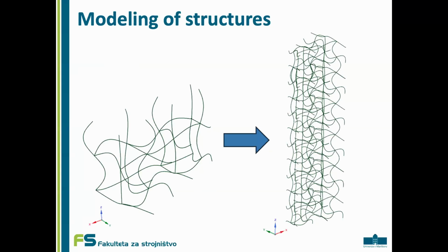So, modeling these structures, we didn't use the entire geometry. We only used one slice of the entire cylinder because they were symmetric. So we modified a Python script that was made to give us one row of unit cells with struts to connect them to the neighboring cells. We then used linear patterns and mirroring to create this large, tall wireframe structure that is comprised of 11 cells vertically and 3 struts horizontally.